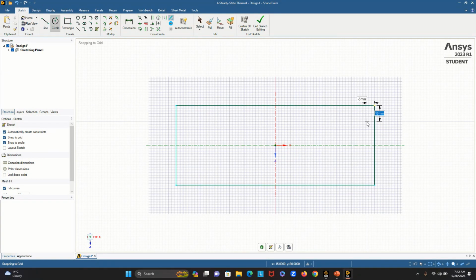And now we will simply click with our mouse, and we've defined our space where we want to drill the hole. From here we have to define the diameter for the hole, which will be 5 millimeter as well. So we'll define it and press enter. So we got our first hole.